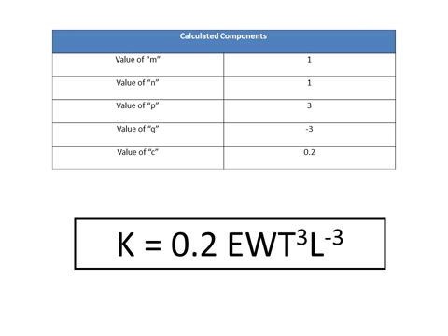The eventual result of this was the calculation of 21 different C values, one for each deflection performed. Although the C values were different for each deflection, the difference was not extremely significant. For this reason, an average C value was computed using the 21 different C values previously calculated. The average C value was 0.1904, which was rounded to 0.2 in the final equation.